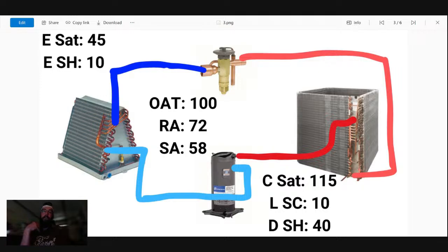And for me, if that was me in this case, it would be a reasonable assumption that the company that came out and did the prior inspection, maybe their technicians just weren't as experienced or as well trained, whatever the case may be. So they saw the low speed on the fan during the inspection. The technician, from the training he's had, thought he was doing a good thing. He thought he was helping them because he was taught a rule of thumb that for cooling mode, the fan should always be set to high, and you're going to get your best performance in that state.